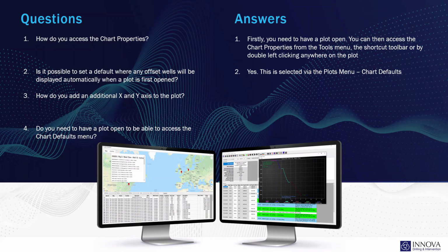Question number 3. How do you add an additional X and Y axis to the plot? By right-clicking anywhere on the plot, the option to add an additional X and Y axis will be available at the bottom of the context menu.